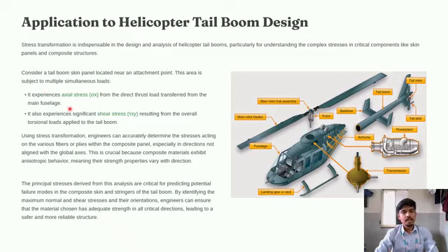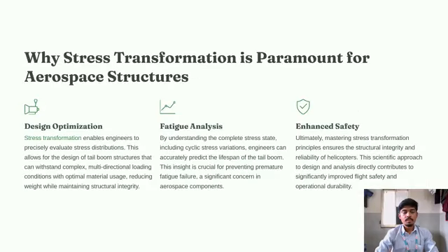It experiences axial stress and shear stress, which result from the overall torsional load. Using transformation, engineers can accurately determine the stress acting on the various fibers or plies within the composite panel, especially in directions not aligned with the global axis.